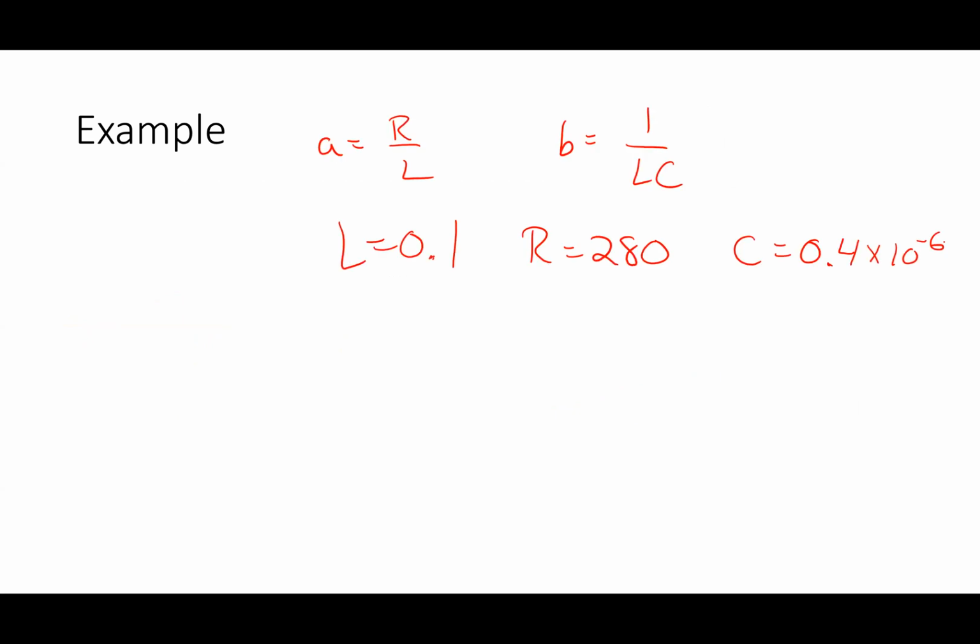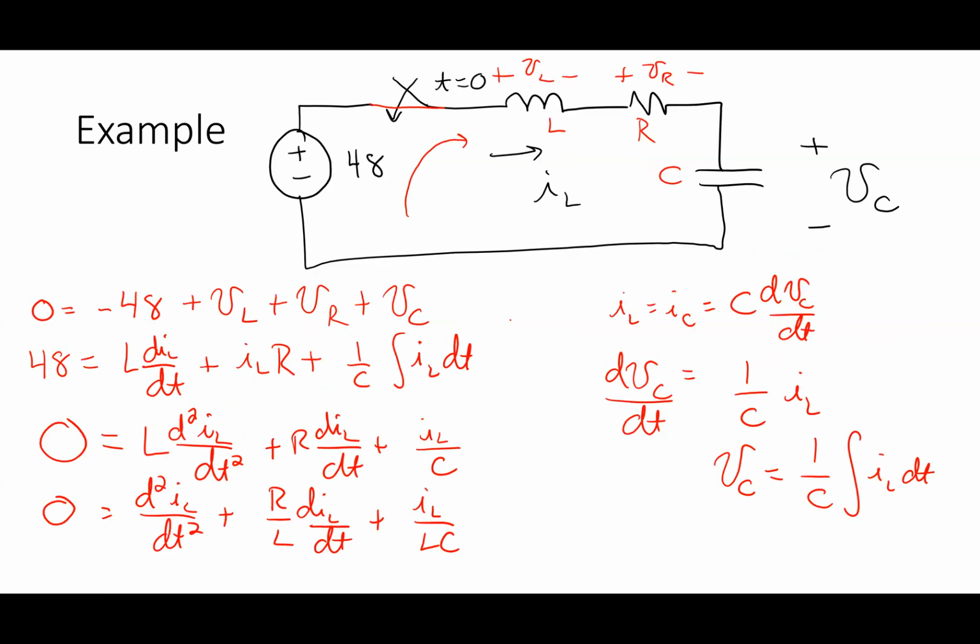So to get the form of the solution from this, when I say the form of the solution, what do I mean by that? What am I trying to find? Yeah, what's the transient? Specifically, what I'm trying to figure out is, is it underdamped? Is it critically damped? Is it overdamped? Right? So the key thing is I had this relationship where I said the roots of the characteristic equation were negative alpha plus or minus the square root of, which order is it?